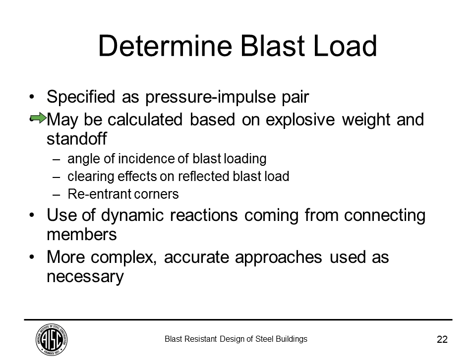There are many tools available for doing that. I mean, there are charts that allow you to figure out the incident impulse and pressure and then convert that into a reflective pressure and impulse. But in today's blast resistant design world, there are enough tools available that you should be able to just plug in a number and get the loads that you need for your design.